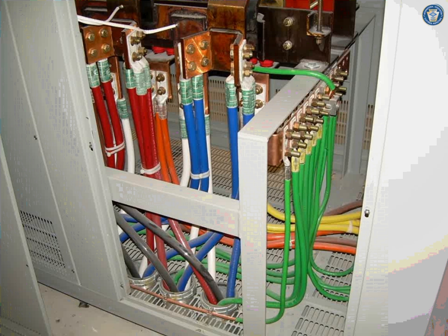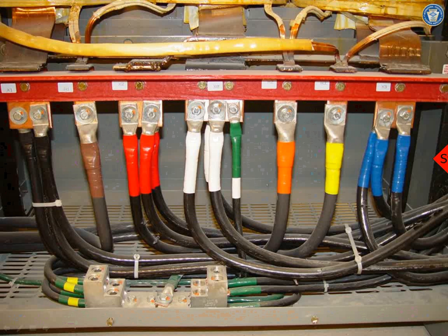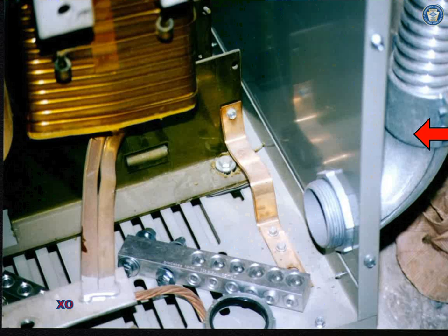Here's your transformer separately derived system, bonding your neutral into the ground bar, neutral bar to the ground bars. Here's your system bonding jumper where the X0, is it X0 or X3? This is my neutral, supposed to be the X0 here, tying it to the ground bar that we're just looking at. You guys will see all the time. Inside the transformer here. Here's the same thing inside the transformer.